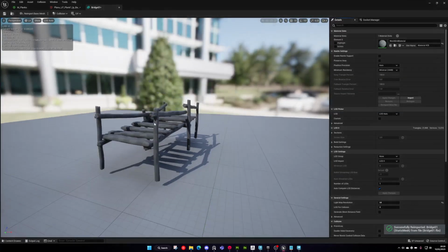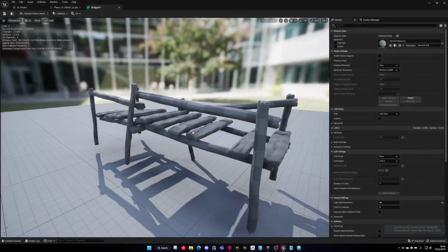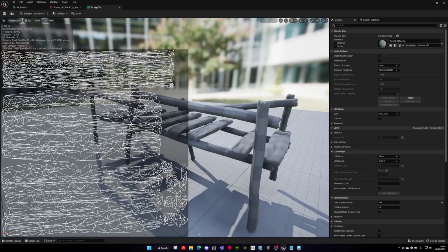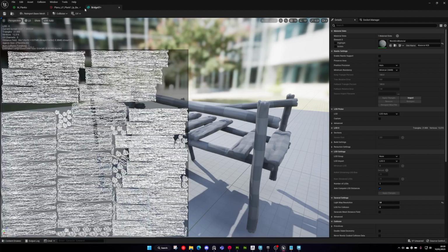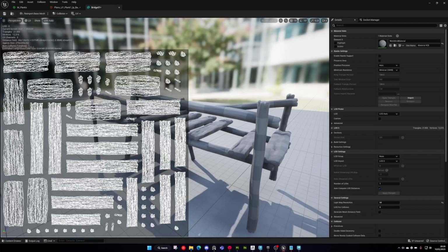If we open it up, depending on what our import settings were originally, we're going to have a third UV channel. So 0 is 1 in 3ds Max, then 1 is 2 in 3ds Max, and then this 2 is one that is made itself. So if we look at 0, this is like our regular texture one. 1 is the one that we just made, and 2 is one that it tried to make itself for light maps. And that's just because of a setting that we had.